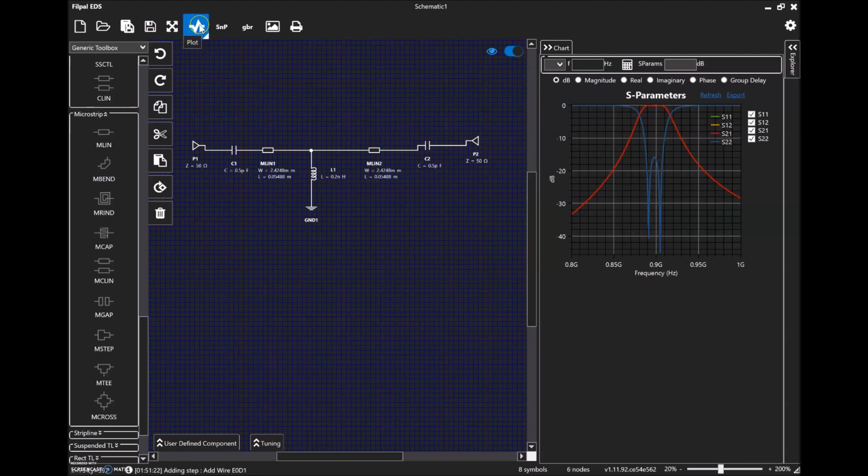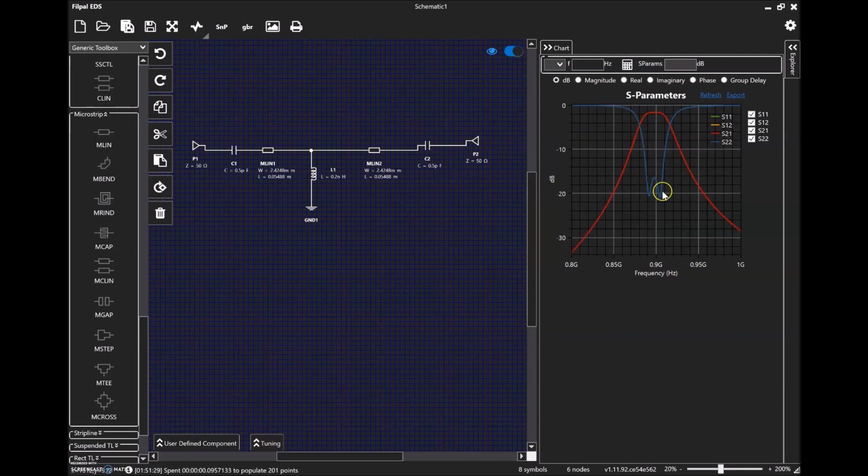So now if you click on the simulation button, it should give a two-pole response. You can still observe the two resonances pretty close to each other, and you can achieve a return loss of a minimum of 16 dB. However, you find some significant loss at the passband, 1.64 dB insertion loss. This is basically due to the loss tangent of the substrate, as well as the finite conductivity of the copper that we define for the Microstrip.